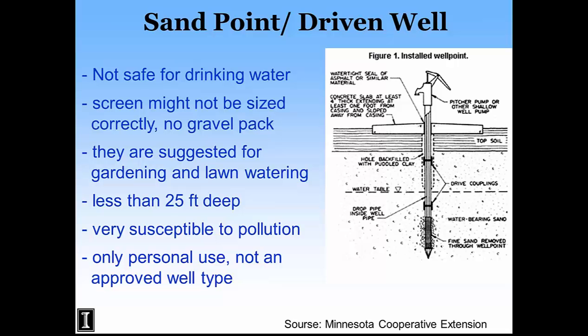And in many cases, folks who have tried to do this end up having to have a driller come out anyway in the end to put in a proper well for them. I wanted to mention this because they're really not safe for drinking water. This example shows topsoil. It doesn't really say how much, but a lot of times that's not very protective. And if you have shallow sand near the surface where you put a sand point, then the topsoil is very sandy as well. So you have a lot of infiltration.